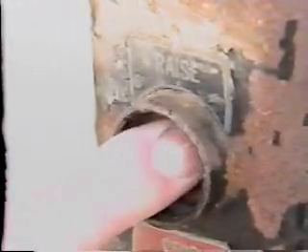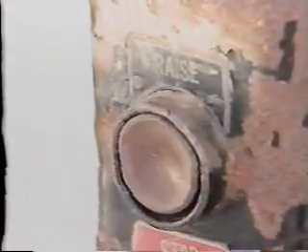Now have the gate raised so that you can inspect the upstream side. The gate should go up smoothly and evenly. Watch for any jerky, erratic movement. Check the bottom seal for cavitation and other damage. Scan the upstream surface area for any broken, missing, corroded, or loose seal fasteners. Badly corroded or broken fasteners should be replaced.